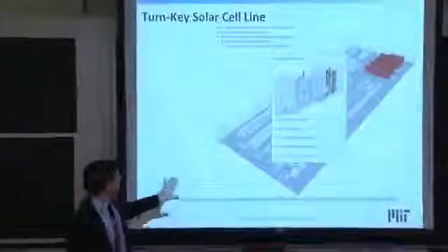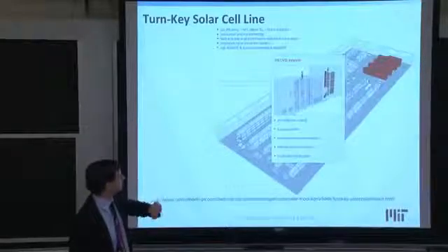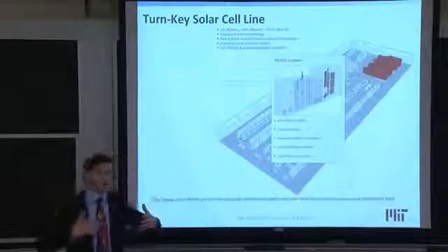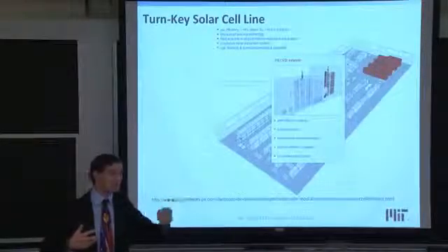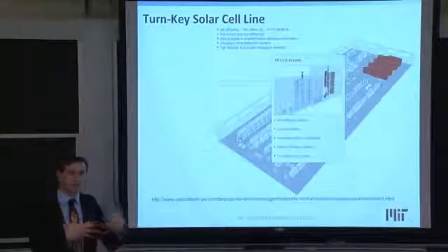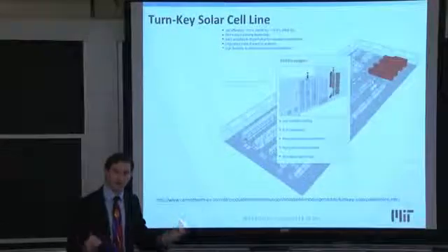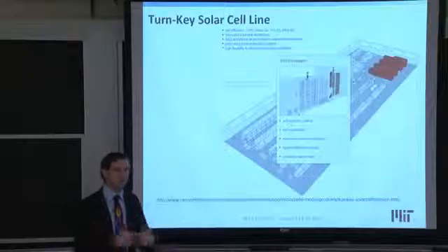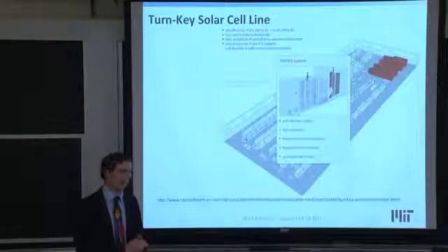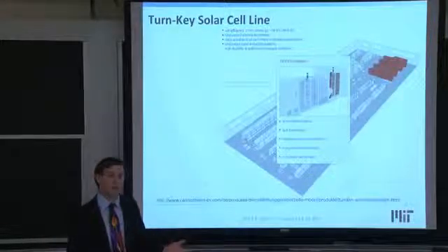So the next step, after we have our p-n junction, would be to create the anti-reflection coating. And this is done by a process called plasma-enhanced chemical vapor deposition, or PECVD for short. And in the PECVD process, you flow in silane gas and ammonia. Silane is silicon with a bunch of hydrogens, 4 of them. And ammonia is nitrogen with a bunch of hydrogens. And the nitrogen and the silicon react on the wafer surface and create a silicon nitride coating. The hydrogens, 90% of it evaporates off, but about 10% of it hangs around, between 1 and 10%, goes into the wafer or stays at the interface there and eventually is driven into the wafer, passivating bulk defects.